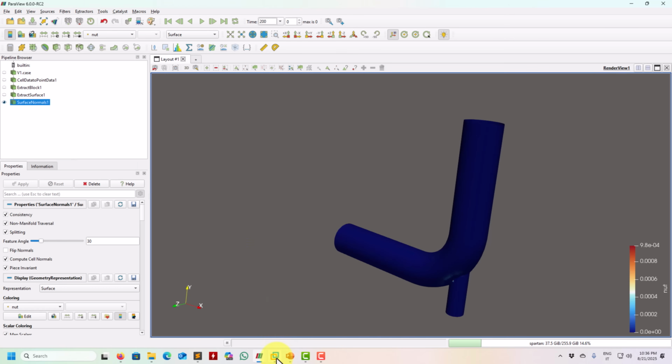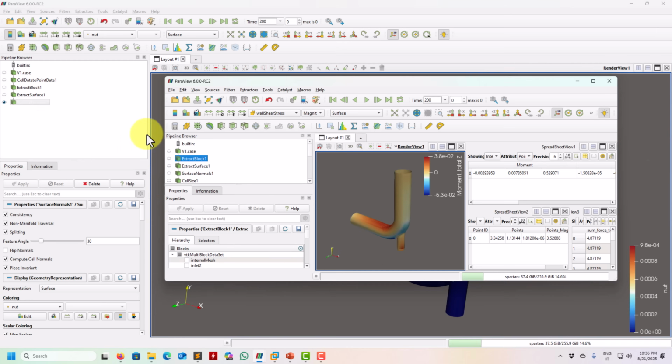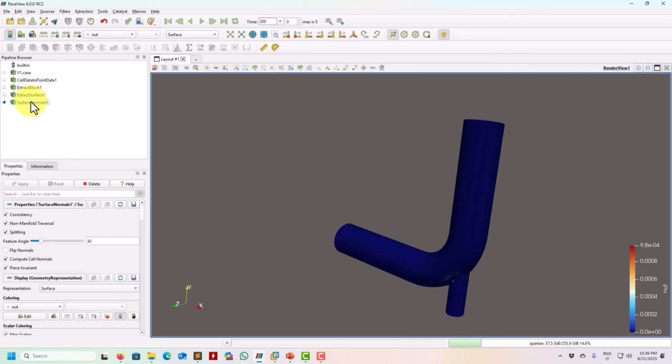So at this point, the next step that we need to do, okay, I have cell size also, because I need the area. Remember to plot on the surface, we need the area to get the right force units. Because you get pressure, let's say pressure in Pascal, but that is not the pressure distribution. You need pressure times normals times area to get your Newtons, okay? So you have a filter here, the Newton, sorry.